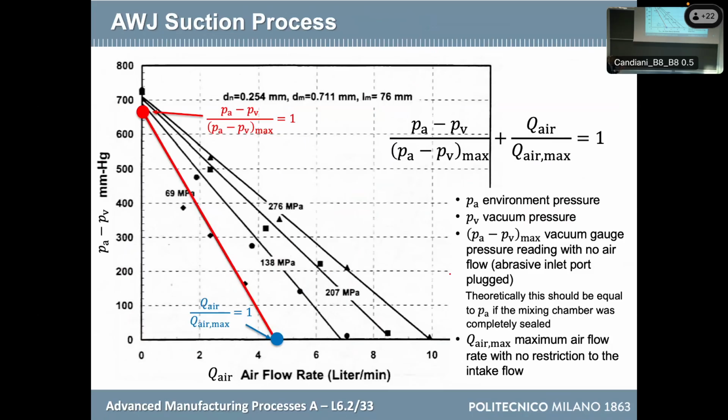If you remember at the beginning, yesterday, I said that when you think about the hopper on board of the cutting head, I needed to suck also some air after defining the amount of abrasive. Otherwise, the amount of abrasive flow rate would be coupled with the amount of pressure. And this is the explanation of that. Because if I increase the pressure of the water in order to be more powerful, the pressure will suck more air, and more air would mean more abrasive.